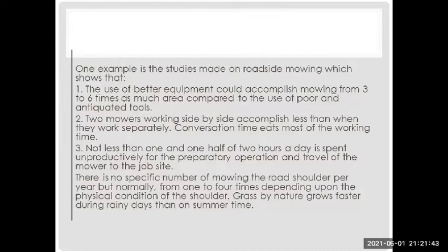There's no specific number of mowing on the road shoulder per year, but normally from 1 to 4 times, depending upon the physical condition of the shoulder. Grass by nature grows faster during rainy days than in summertime.